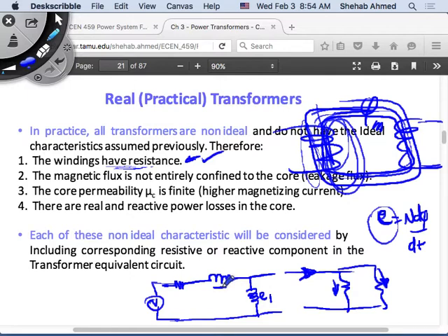Versus here, no. The voltage across that's developed due to the leakage flux linking my coils. This is leakage flux flowing in the air. This flux is linking a certain number of turns. If it's linking turns, that means there's voltage developed across these turns. This voltage is actually not used to produce my output voltage.